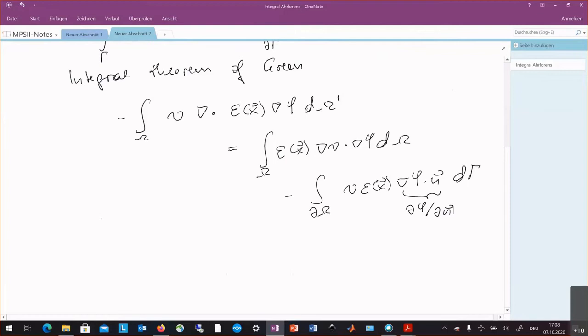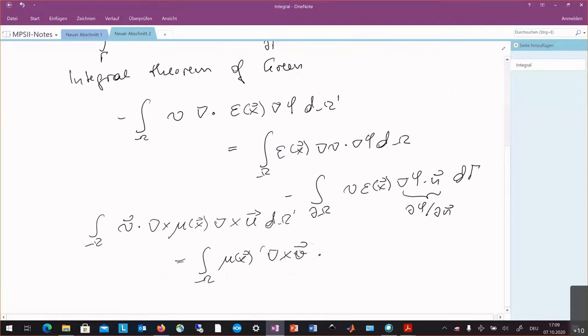So you have here the volume integral of a test function, which is a vector, and we have the curl. Now I use here already the permeability being a function of x, the curl of u, which would be in our case at the end the magnetic vector potential, and that you can rewrite as a volume integral where we have here the permeability without any derivative, and we have the curl of v dot product with the curl of the unknown u d omega.